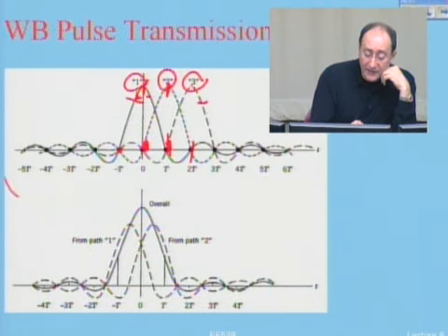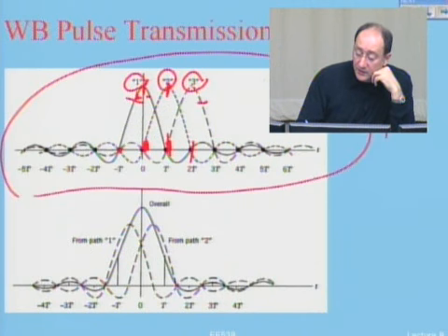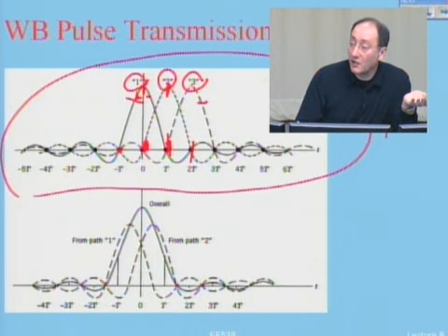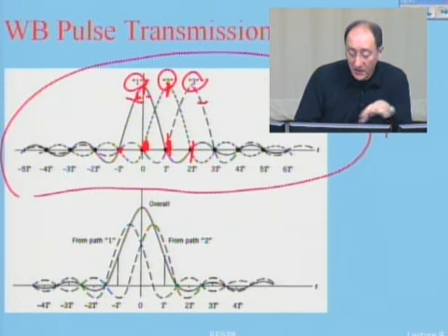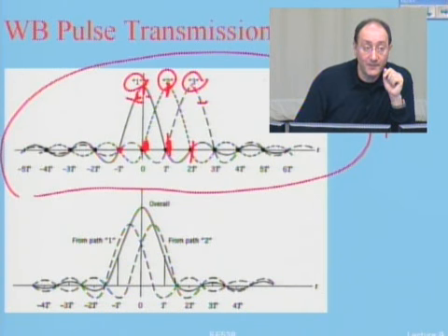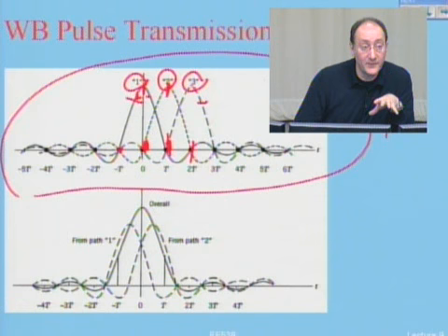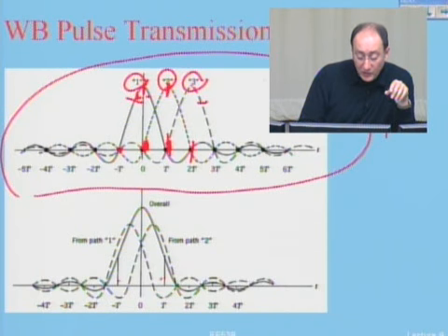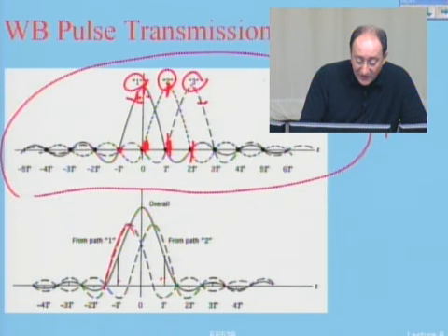Now, if I have narrowband communications, I send a pulse, I receive the same pulse, raised cosine pulses, no problem, similar to voice band modems, and they are very good. I can use them. Okay? But how about if I have wideband communication? In wideband communication, I know that if I have two paths, the two paths are apart on the order of symbols. So I send a signal, I receive one path here and one path here, and the overall received pulse is something like this.